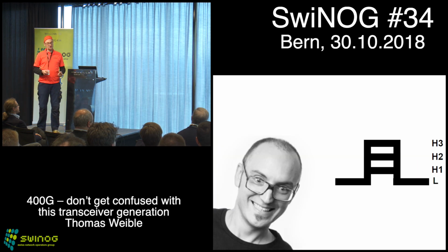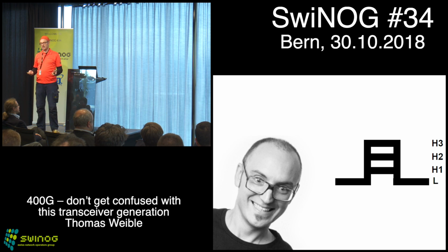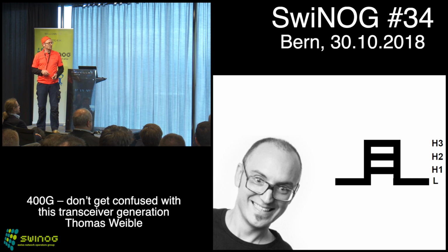Now, as I introduced at the beginning, we are talking about 400 gigabit, and what you have seen so far on the theory part is more the technology from 100 gigabit. Now, for 400 gigabit, it looks a little bit different, and we still take our rectangle shape here, but what we did, we added 2 additional intermediate steps. And some of you might be familiar with that technology. It's a modulation method. And so the great thing now about this modulation is, instead of 2 events, the high and low, we now have 4 events.